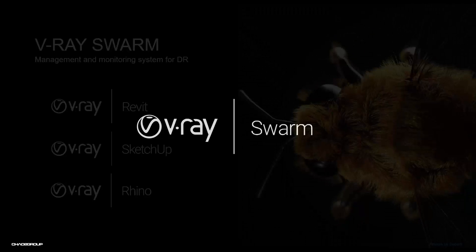In fact, it's designed primarily for Revit. You have Swarm in Revit, SketchUp, and Rhino. It's very powerful. What you need to have is Revit and V-Ray on your workstation, the master computer. And then for the slave machines, for the other machines, for the hardware resources, you need to have only Swarm installed. You don't need to have Revit.